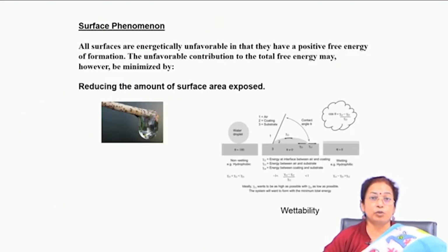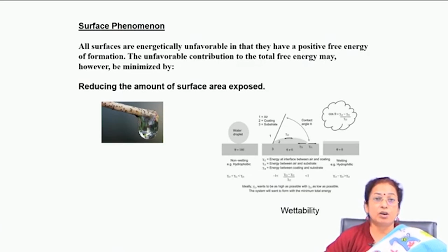Among the different phenomena influenced by the surface energy is droplet dimension. When you pour molten metal, it pours in a droplet-like fashion. Otherwise, when you prepare synthesized powder by water atomization or gas atomization, you will find that its shape is always spherical in nature, because when it is spherical it has very low surface energy owing to its very low surface area.